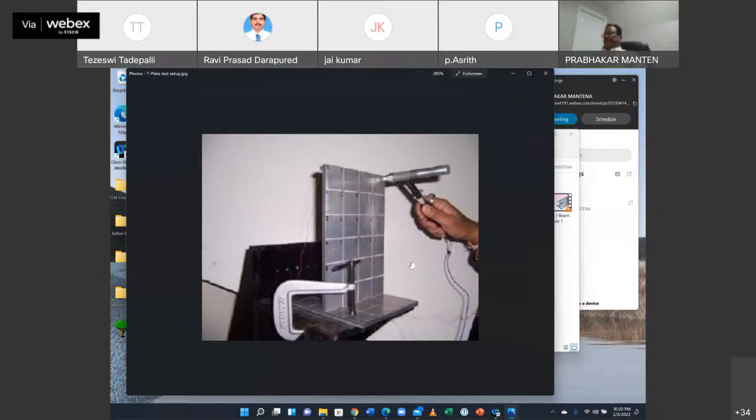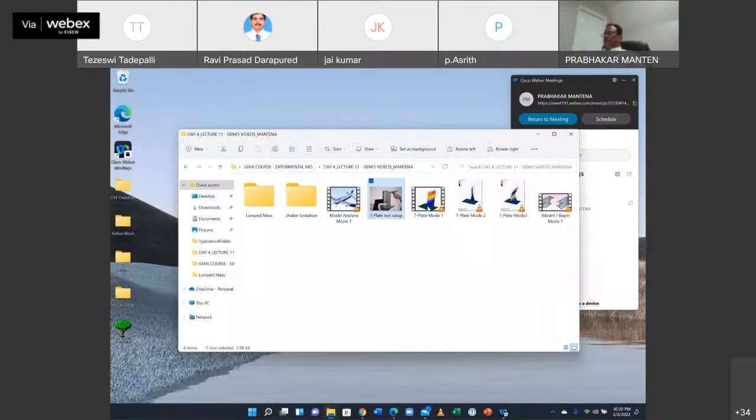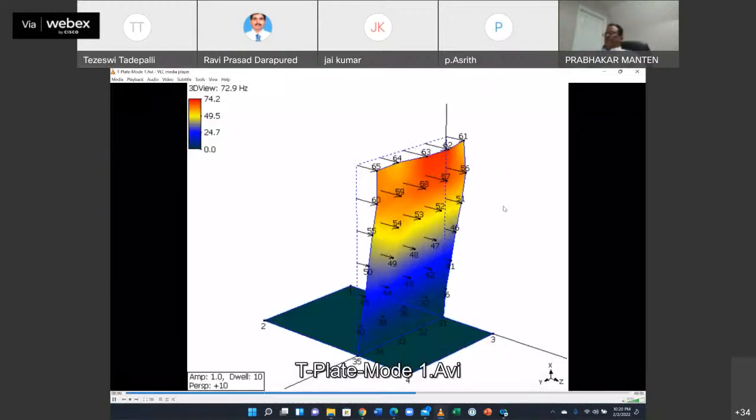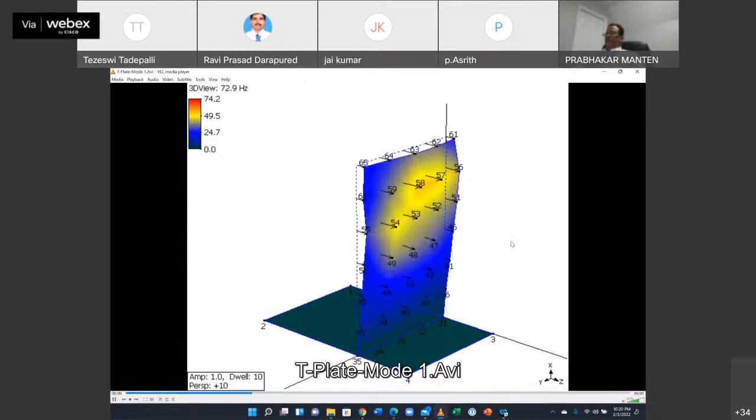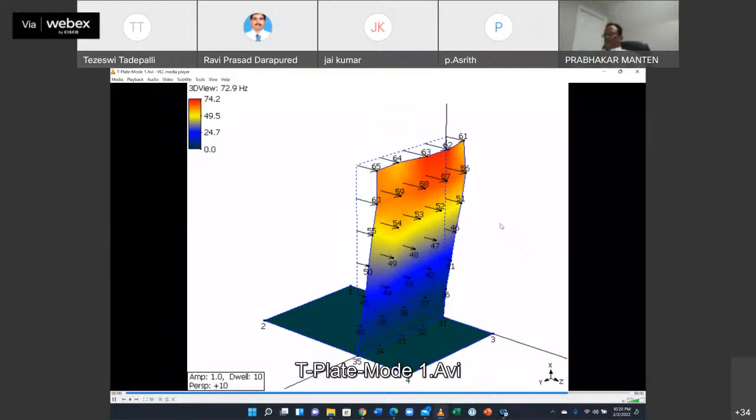But after doing all the tap tests, and all the data is collected and analyzed, the feedback gives you the actual modal patterns shown on the software, the fundamental mode. You see that back and forth, it's supposed to be all the way. Fundamental mode, back and forth, back and forth. I think I got it. It's around, where is that? Hertz. 72.9 hertz. The fundamental mode of the plate going back and forth.